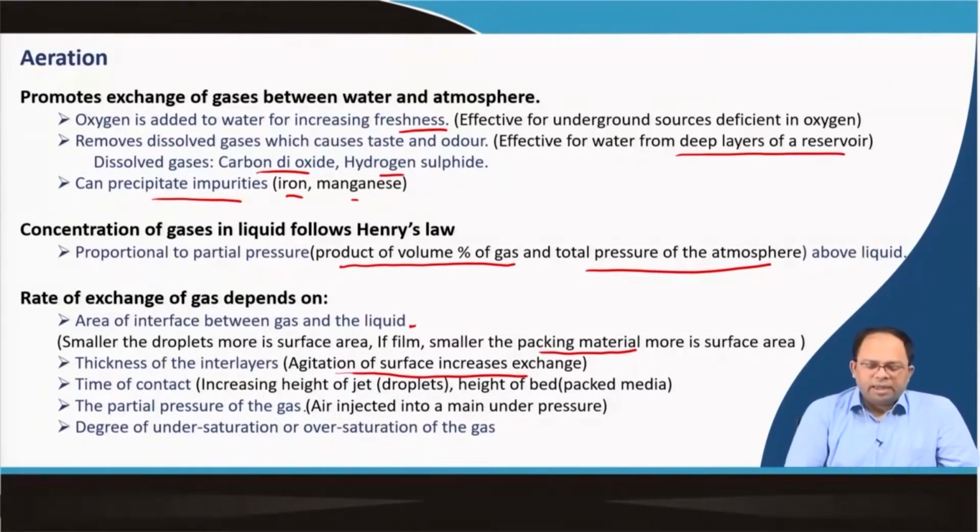Then the time of contact. How can we increase the time of contact? By increasing the height of the jet or droplet. If I spray the water from a higher height, obviously it will take more time to fall down, so it has more time in contact with air. Or in case of packed media, if its height is raised, the water passes down through the media and has more time in contact with it. That also increases the time of contact.